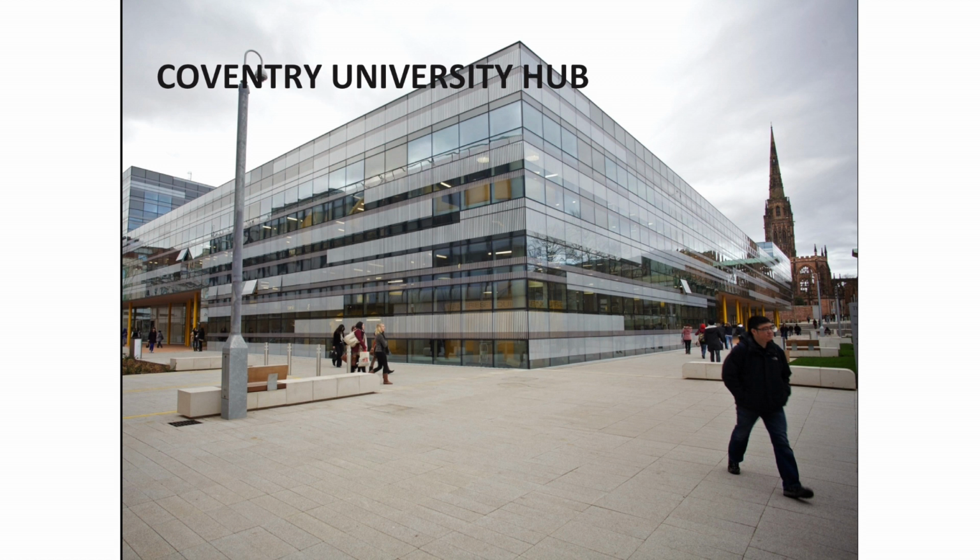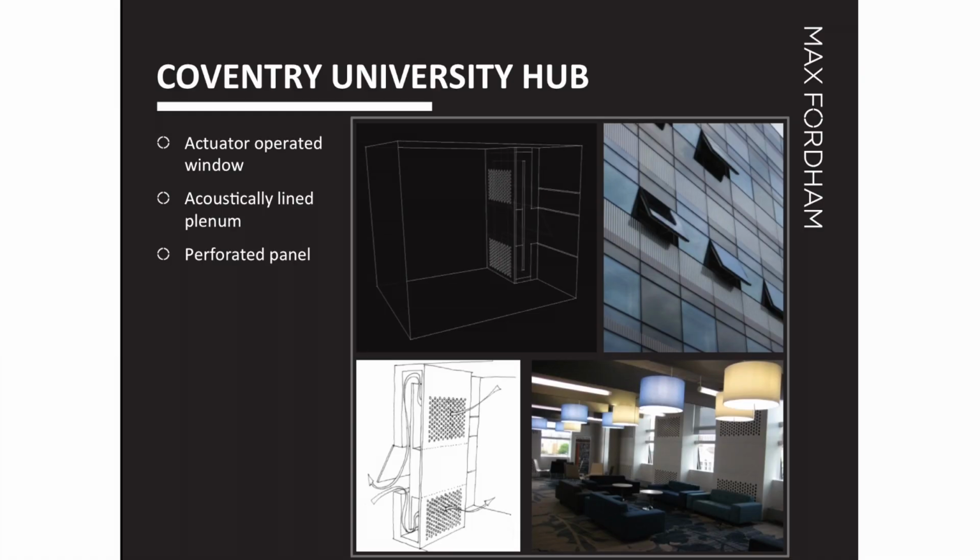A further example is Coventry University, and this achieves the highest performance. It is a circuitous path, so the air enters here through an opening window, and it goes down through this, enters the room through this perforated panel, and then it warms, goes up, and goes out again.